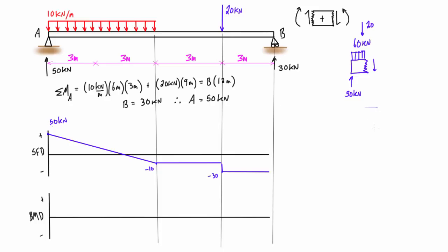So if we consider the free body diagram from the other side, if we section just to the left of that support, we're going to have 30 kilonewtons pressing up from that reaction force, and we'll have some shear force. That's going to have to be 30 kilonewtons pressing down in this region, and when we look at the left hand side of a cut, positive is in the upward direction, so that's going to be negative 30 kilonewtons. That's exactly what we're seeing for our shear force right at the end there, negative 30 kilonewtons. Alright, so that looks like we've done that properly so far.